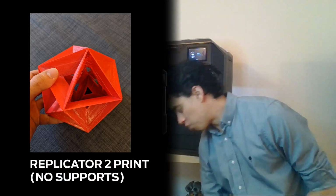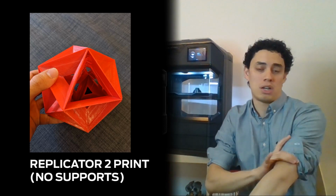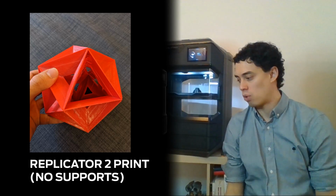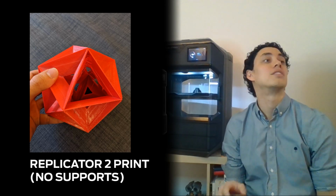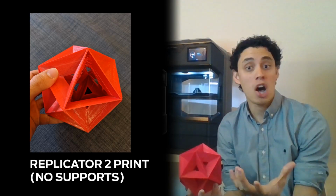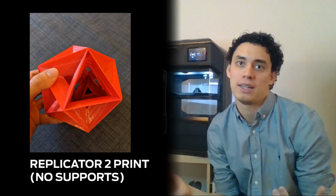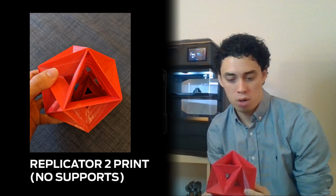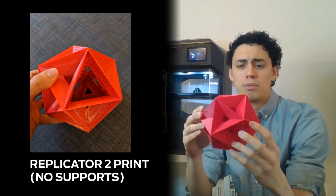Coming back to other examples of printed files, right? A lot of people, and actually a lot of my friends, came to me asking, well, why wouldn't I get just a basic Rep Plus printer? And the Rep Plus printer is an amazing machine, right? We've had it for probably over 4 or 5 years now. I still have it, but it's actually in storage right now because I'm focused on the Method printer. It's an awesome machine, but it's a single extruder machine, which also means that you can only print material in support in the same material that you're printing the part at, or choose not to have supports, which is what happened on this part. So this part I printed on a Rep 2 actually.